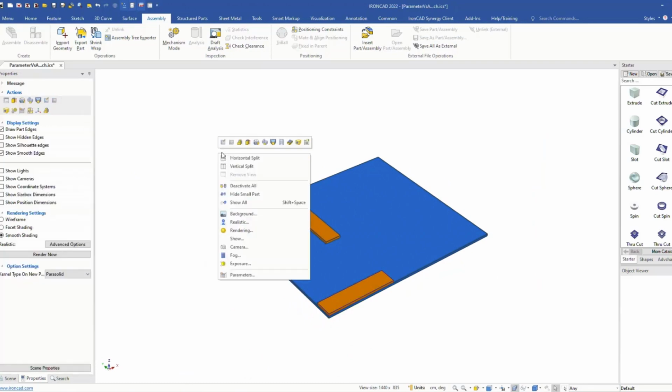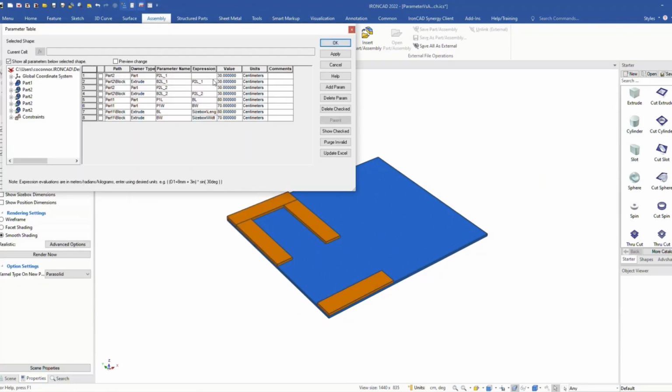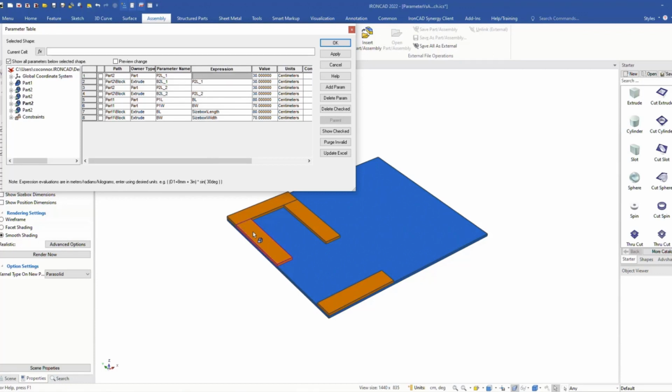So now we've got all these positioned on this face, but we need to do the parameters. So now we'll go into our parameter table, and we'll have to look and see what we've got here. We have a bunch of things that are copies inside of here. Since we have duplicates, I'm showing all of them. So we can see that there are these added P2Ls, underscore 1, underscore 2, because it's creating duplicates of these parts, which is fine. We can rename those to make it clear, but we can just select on these to see what we've got. So we've got this particular part, which is showing this one, and this one over here is showing that. So this one is the one we want to drive first, which is going to be the same as our part 1 length. So we're going to type that PL1 there to drive that.